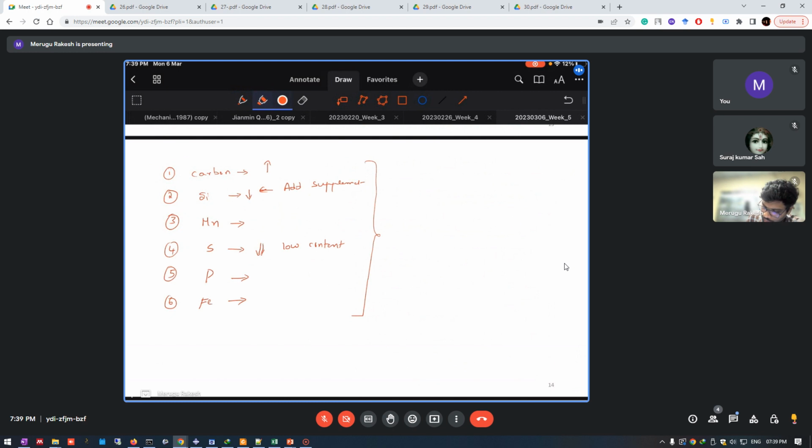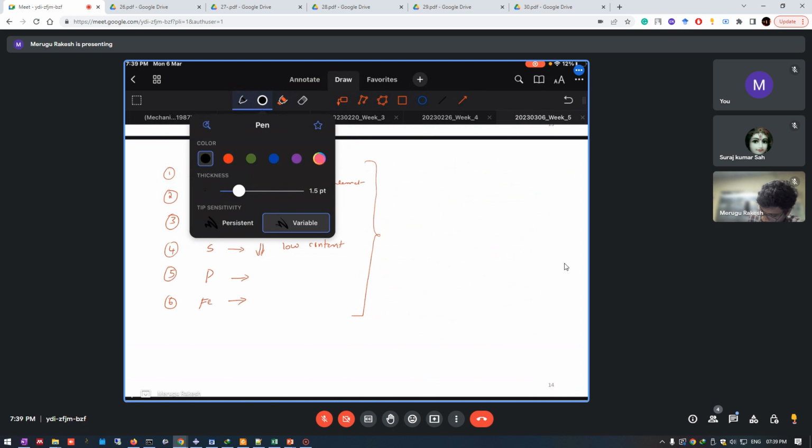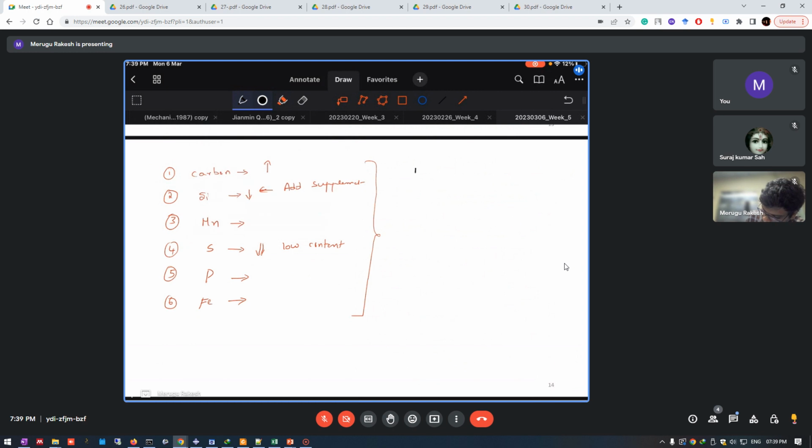Then we need to take care of some of the parameters we'll discuss. The first parameter among them is coke rate, which as I discussed, for every 8 kgs of ore, at least 1 kg of coke is required. This is the coke rate. Then the second one is blast rate. So at what rate you are using this blast, so that the combustion process is controlled.